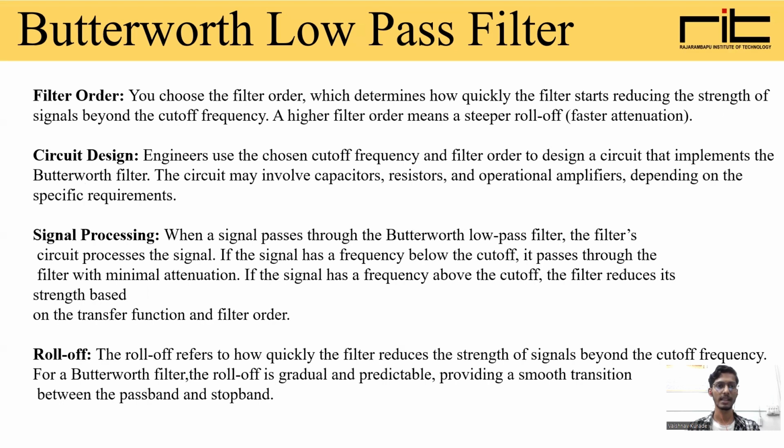Then there is a circuit design. Engineers use the cutoff frequency and filter order to design a circuit that implements the Butterworth filter. The circuit may involve capacitors, resistors, and operational amplifiers depending upon the specific requirement. Next, there is signal processing.